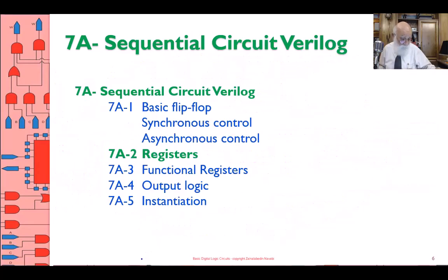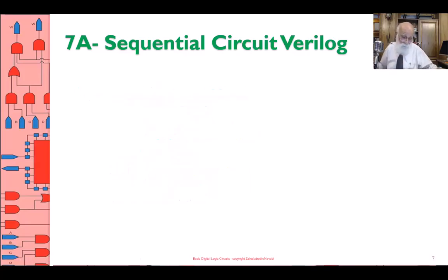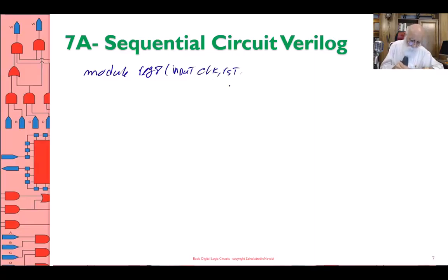All right, let's do registers, where there is really not much to registers, except that instead of 1 bit, you make it multiple bits. So let's go back to this module, reg 8, input, put the clock and reset first, and then you put your input again, this time 7:0. Okay, call it, you want to call it parallel in or reg in,